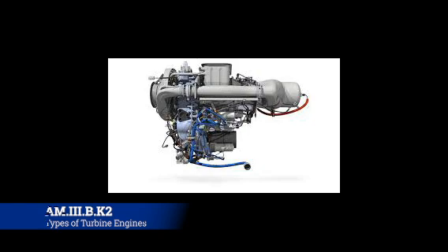Now, the way that it generates its useful power, which the helicopter is actually going to use, is through the accessory gearbox that's on the bottom. So that big gray thing that you're looking at on the bottom right hand side of the engine is actually the starter generator. Just to the right of it is the circular port that has these teeth in the gear. Well, that then marries up to a shaft which turns, and then turns the transmission, that turns the actual rotor head and all the good stuff.